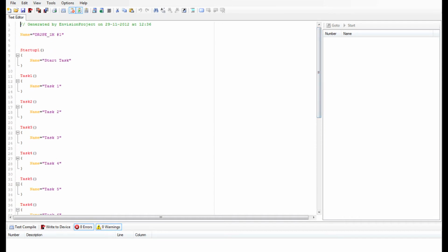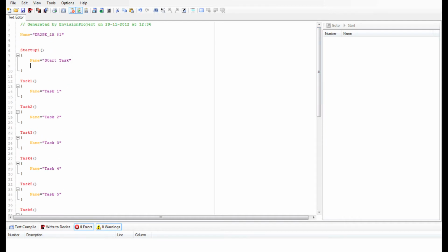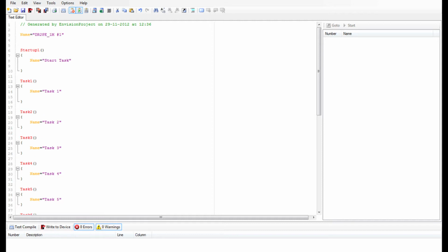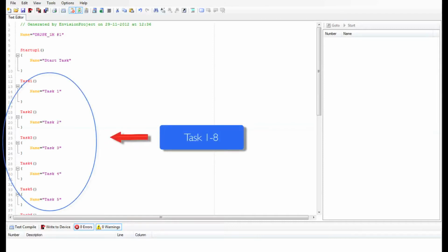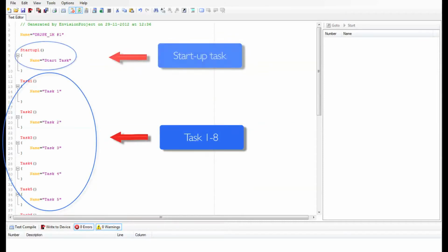Each of our 9 series panels will have this functionality. You can also save tasks on the load controllers, sensors, time clocks, etc. For each panel you can write 8 tasks and 1 startup task. The startup task will run when you reboot or lose power to the network, so it is not dependent on a button push.